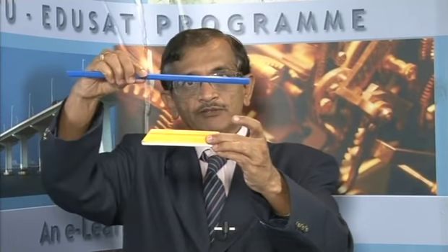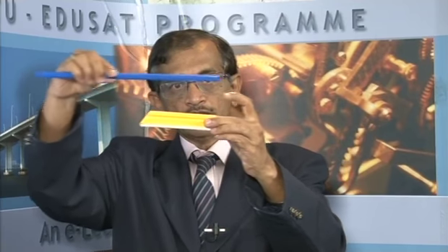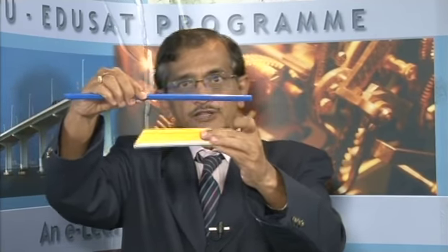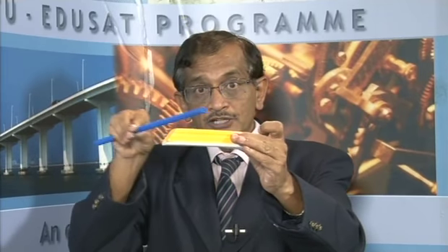You may be thinking, what is this? I will show you the example. Say this is the bed of a river, and this is my depth. Here to here depth is 1 meter, here to here again 1 meter, everywhere it is 1 meter. So I am marching with space, maybe 100 meters, maybe 100 kilometers, maybe 2 kilometers, whatever. Everywhere depth is the same, everywhere velocity is the same, everywhere acceleration is 0. So definitely we can say it is a uniform flow. So uniform and non-uniform relate to the space x, y, z, marching in the space.